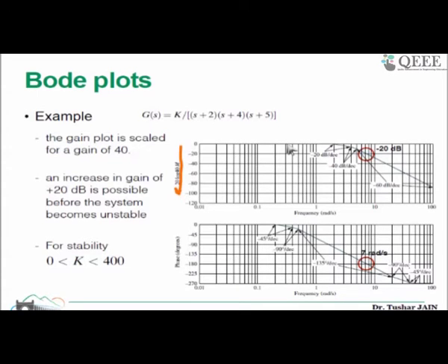Regarding this, before starting the Nyquist plot, let's take a couple of queries. It says: what is the relationship between stability and the coefficients of the characteristic polynomial? We have seen this: you can see it by writing the Routh table, because we have the conditions there, which are basically functions of the coefficients of the characteristic polynomial.